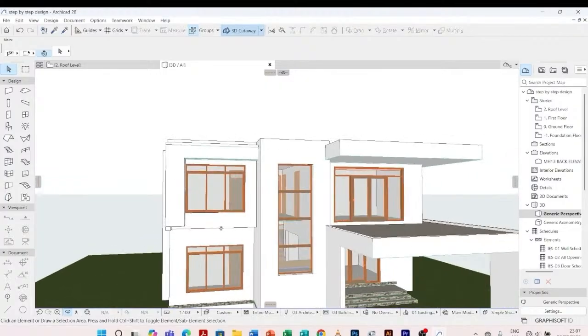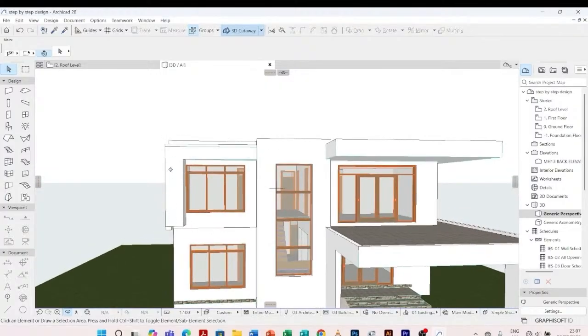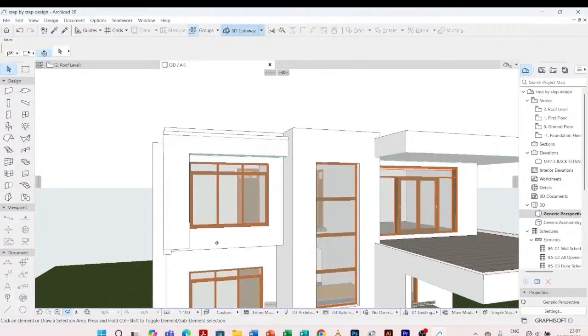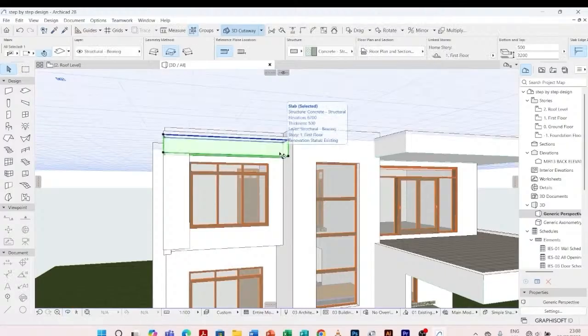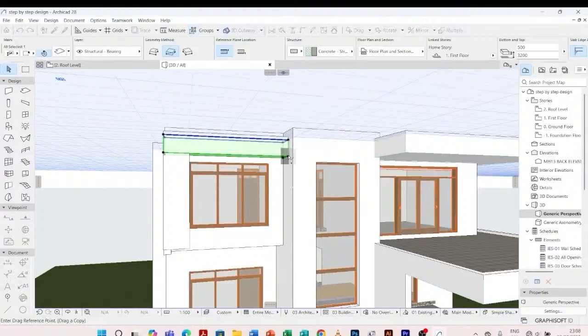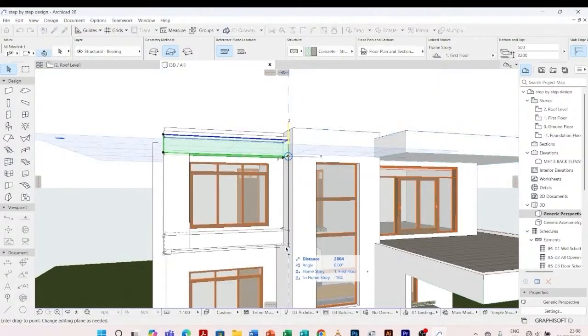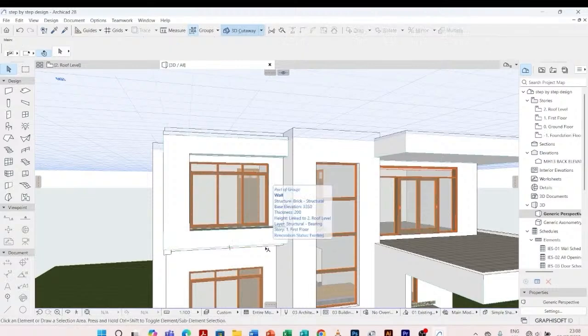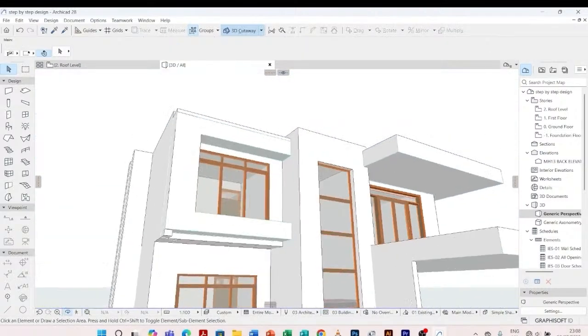Then also down, I'm going to have this slab again, down. So I click on this, I can drag a copy of this. So I'll Ctrl Shift D, that is dragging a copy of this slab. I'll move it down up to there. So I'll go on by adjusting.